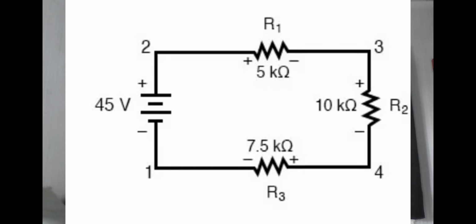The first one, called Kirchhoff's voltage law, or KVL for short, states that the algebraic sum of all voltages in a loop or circuit must be zero, which may sound like nonsense at first because we know even for the simplest circuits there must be voltage for electricity to happen. But if we know, for example, that a resistance is a voltage drop and not a voltage increase, it might make more sense somewhat.